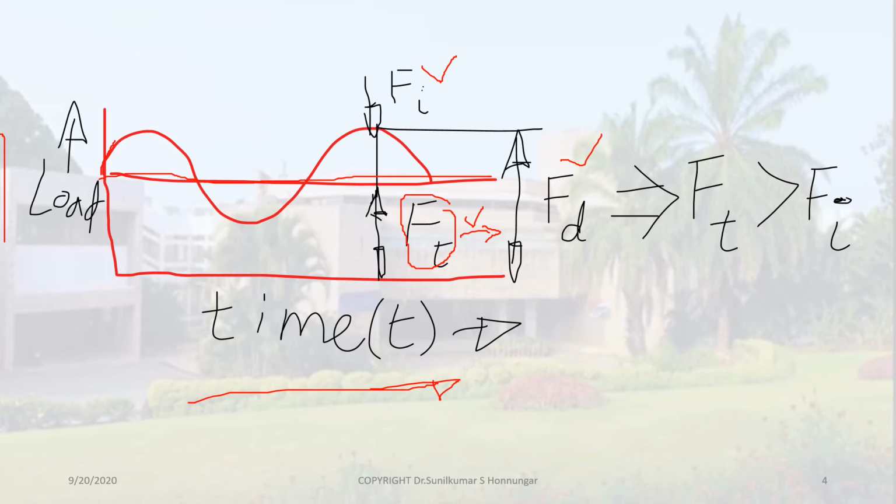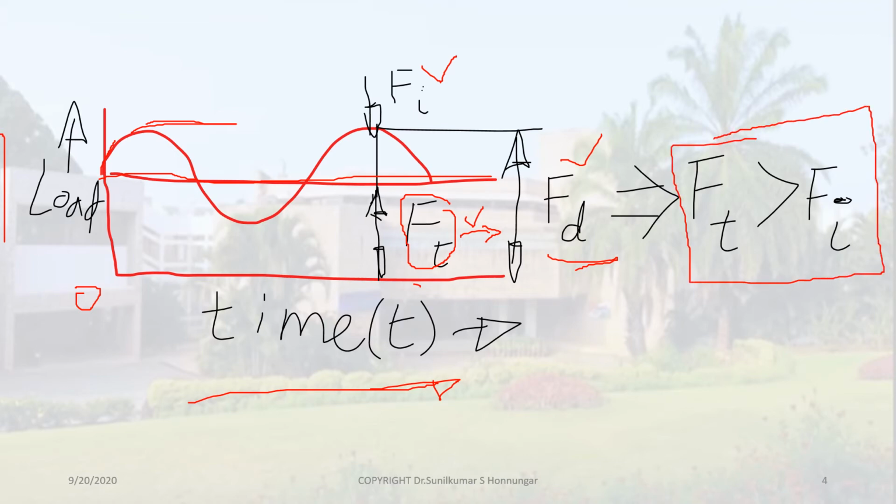Vary means in one particular cycle, you can see the jerks, no? That jerk will be at every increment, thud thud thud, something like that. In a bicycle or two-wheeler or even in a car, you can notice that the jerk is at a particular frequency of time, not continuous, so it varies in a sinusoidal manner. So that is the incremental load. Please note down, the dynamic total is from the zero line to the top, and the amplitude of this particular cycle is Fd, which is given in this particular condition, that is, Ft is greater than Fi.